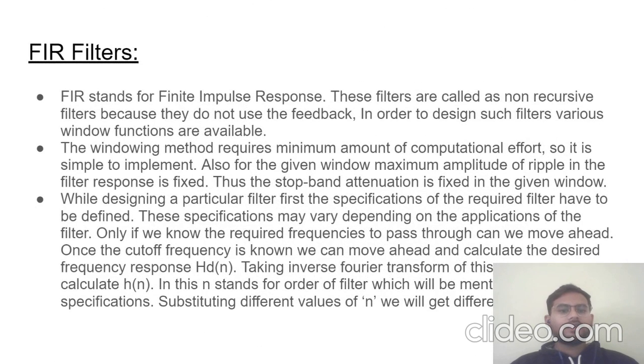FIR filter. FIR stands for finite impulse response. These filters are called non-recursive filters because they do not use feedback. In order to design such a filter, various window functions are available. The window method requires a minimum amount of computational effort, so it is simple to implement. Also, for a given window, the maximum amplitude of a ripple in the filter response is fixed. Thus, stop band attenuation is fixed in a given window.